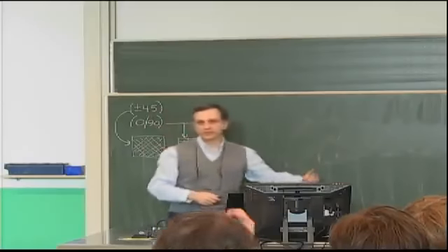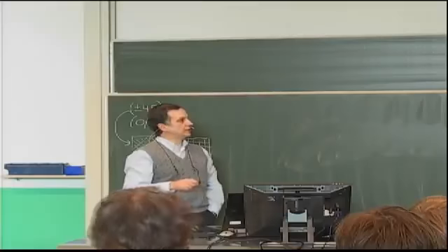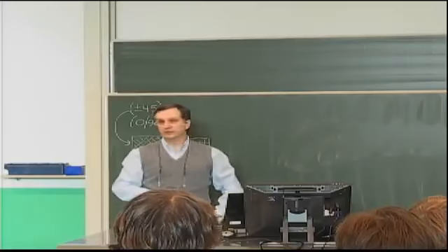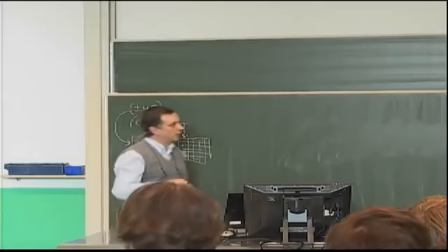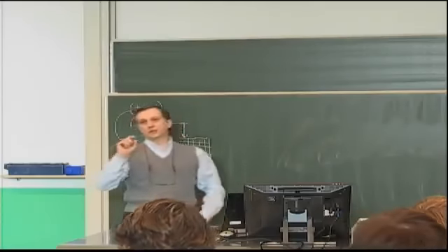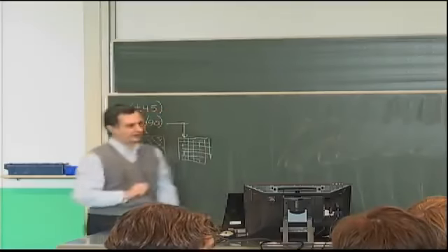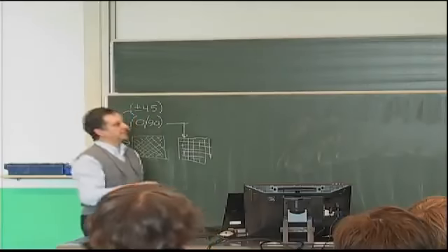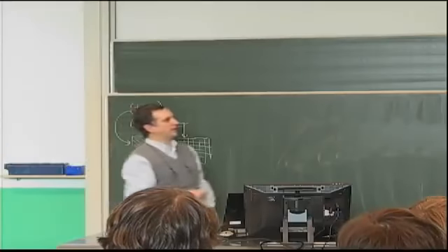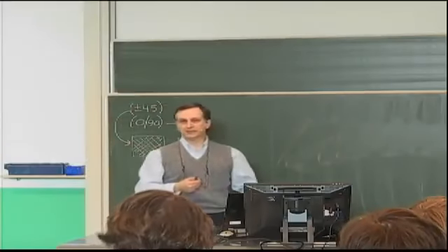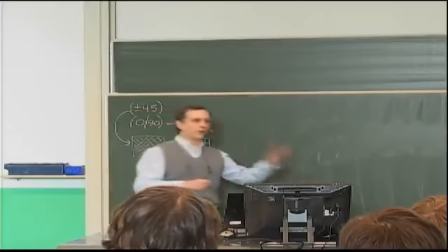The flip side of this is, okay, instead of satisfying the strain compatibility, you choose to satisfy equilibrium. So first you satisfy stress equilibrium equations and all your boundary conditions for forces or moments, but you don't necessarily satisfy boundary conditions on displacements. It's not necessary. Then if you minimize the energy in terms of stresses, though, you will actually, on the average, satisfy the strain compatibility.